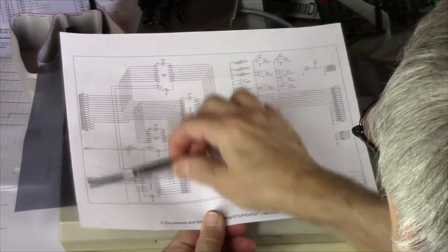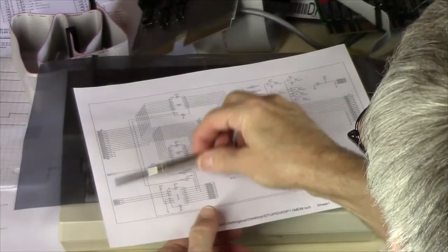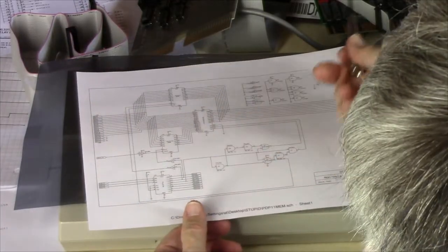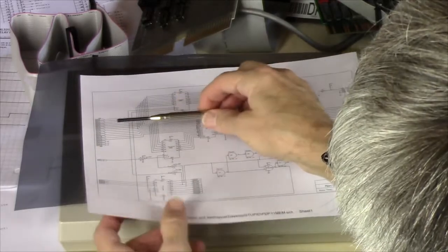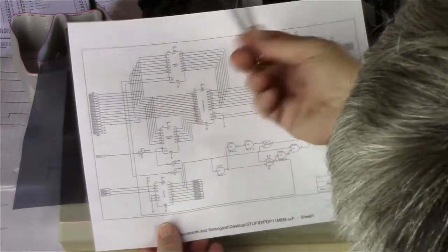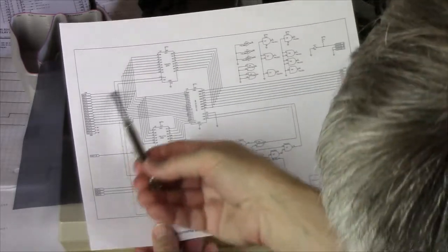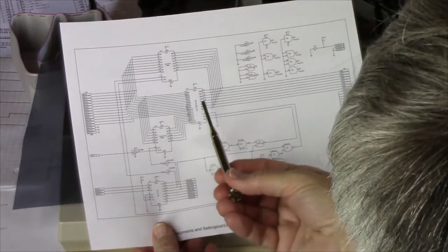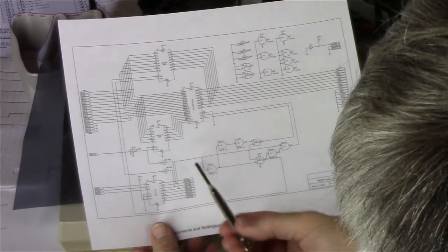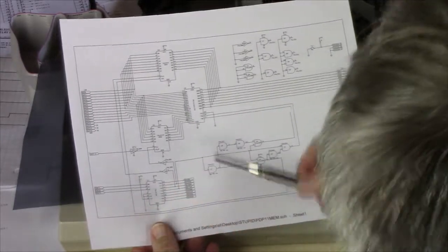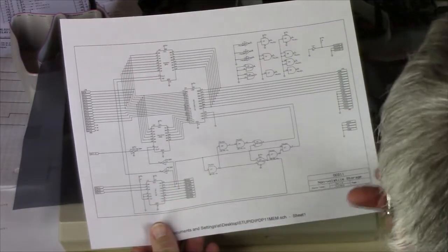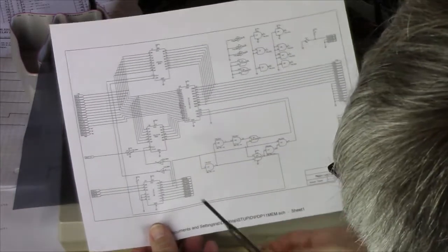Out here you can see this is the bus. These are the interface signals from those blue connectors. This is a 16-bit machine, and it's a 16-bit bus. I'm only using 8 bits. Obviously, I could make this a 16-bit wide thing, and I could add DMA and all kinds of stuff. But again, this will suit my needs.